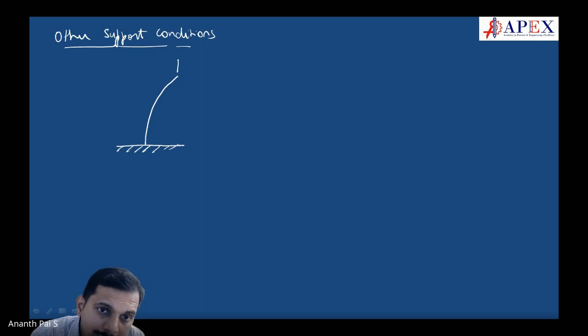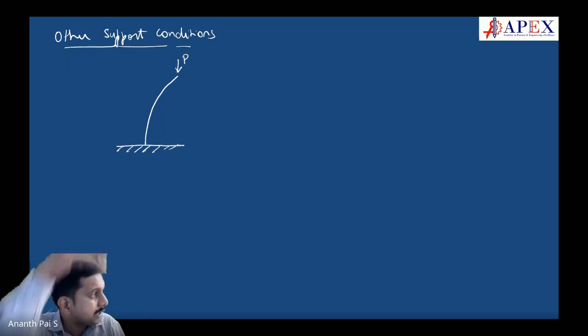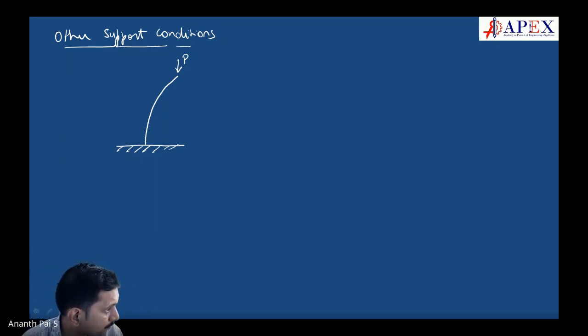See, buckling is related to instability, that has to be understood. It is not the load which is causing the deflection. It's the instability that is causing the deflection, causing the moment. Design is not to have that particular type. It's because of imperfections in the material that it is going to buckle. If it is designed properly, it has to take only compressive loads. It's not happening. That has to be understood.